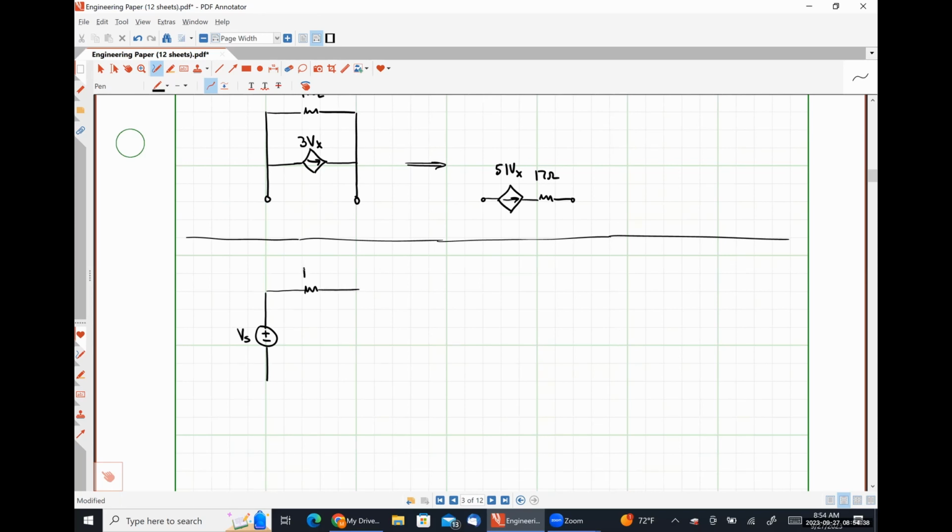So let's say that we have a voltage source Vs in series with a resistance Rs, and this practical voltage source is used to supply power to some load resistance RL. Right? So we know that VL would just be Vs times RL over Rs plus RL using voltage division, exactly what we did earlier today, so nothing new here.